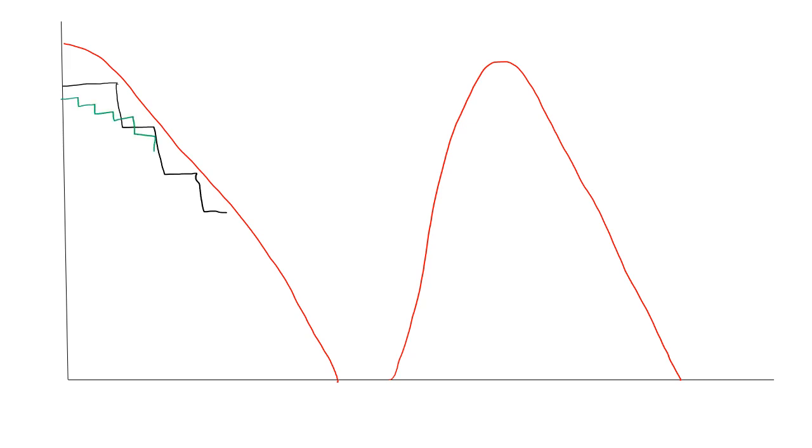It has been observed through experience that an update rate of more than 20 times per second is required to adequately detect the surge. More than 20 updates per second is required.